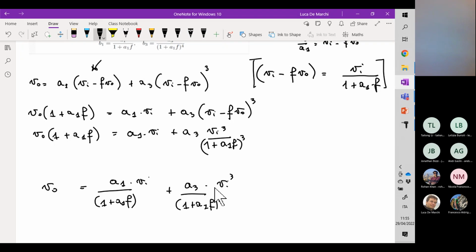We have gained the possibility of having a stable circuit, but we are trading off the bandwidth. Okay. You see the frequency response corresponding to the solid curve was flat up to P1, while now we are basically cutting off all the frequency above PD. Okay, so we have indeed a narrow banding effect.